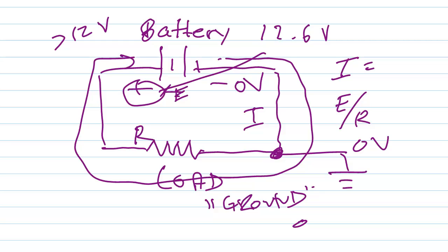So when you talk about a ground in that sense, and I'm talking about a vehicle ground now, not any other type of ground like an earth ground, even if you were to connect the frame of your vehicle to a ground rod driven into the earth so that it really was a ground, you're not going to get any current flowing in and out of there to the circuit here. The current has to have a return path in order to flow.